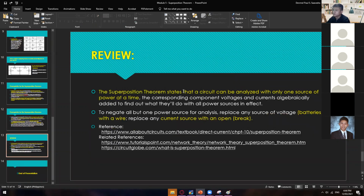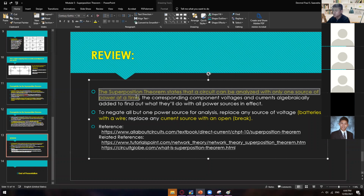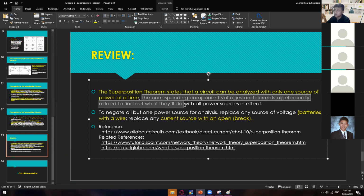And what else? In here, of course, that is the main goal of the superposition theorem. The superposition theorem states that a circuit can be analyzed with only one source of power at a time. The corresponding component voltages and currents are algebraically added to find out what they will do with all power sources in effect. And to negate all but one power source for analysis, replace any source of voltage, for example a battery, with a wire, or simply short it. But if it's a current source, then leave it open, or break it.